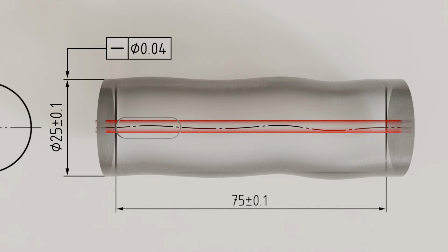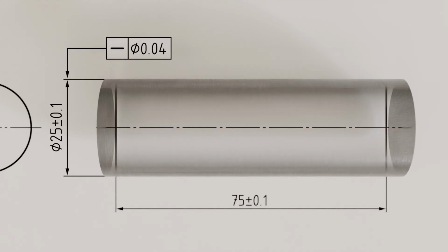One might assume that specifying a perfectly straight axis and a diameter tolerance would automatically ensure a certain roundness of the shaft. At first glance, this seems logical, since it might appear that with a perfectly straight axis and an exactly specified diameter, an ideally round cross-section would naturally result. So if we limit the maximum waviness of the axis by specifying the straightness tolerance and restrict the deviation from the nominal diameter with a dimensional tolerance, a certain roundness should automatically be achieved. But this is a misconception.